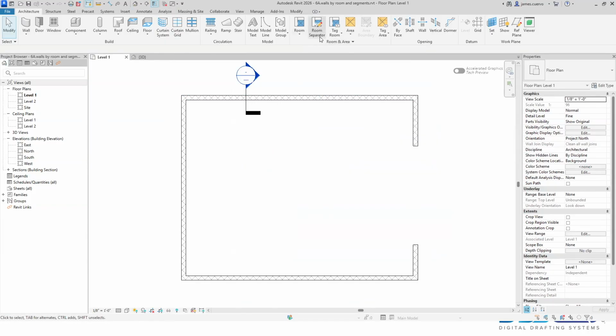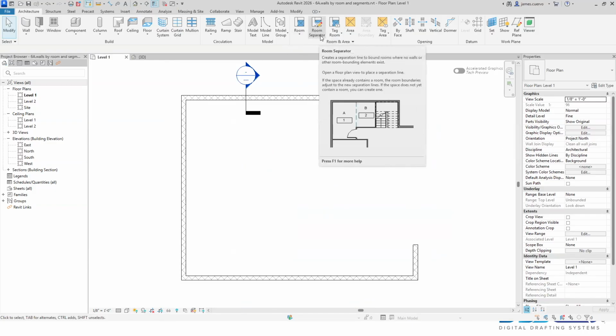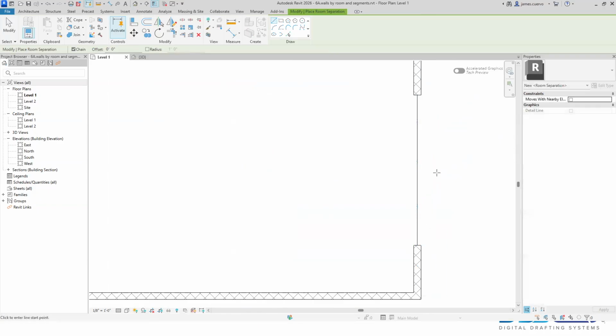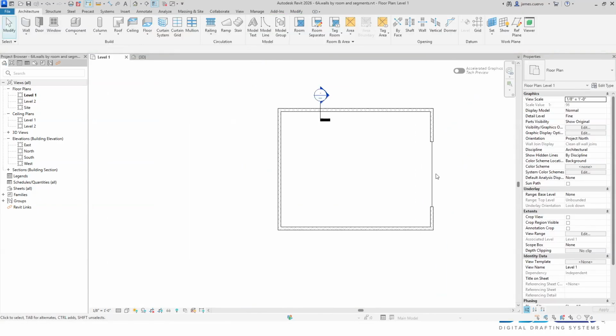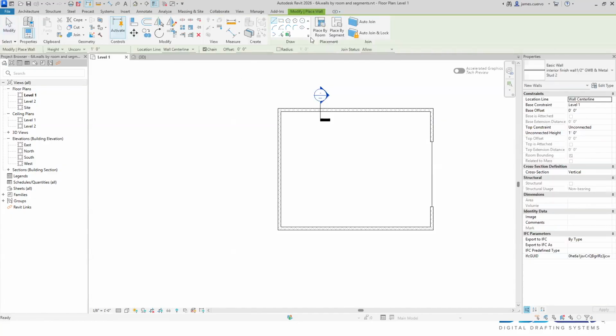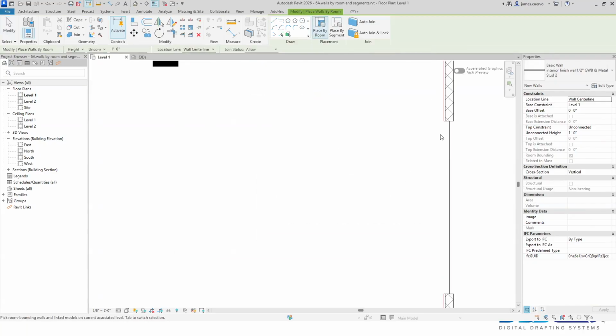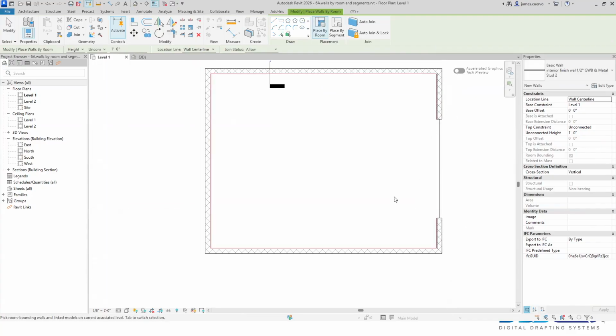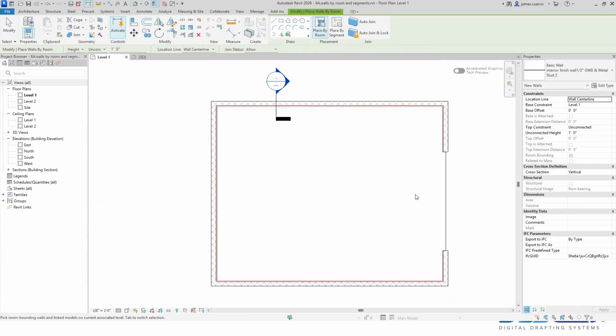We resolve this by using a room separator, which is non-geometrical, but the software knows that the room stops here. And we're going to say to the midpoint here and to the midpoint there. Now I'm using the midpoint on purpose because I want you to see something really cool. Let's place by room. It's a little bit faster. And look what happened. It placed the inner wall and it ends right at the opening edge. You see that? In this case, it's respecting that, which is really cool.